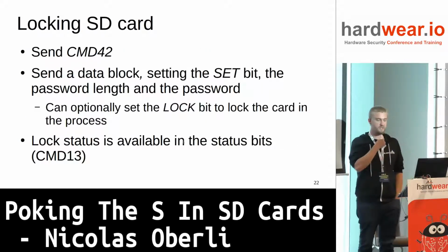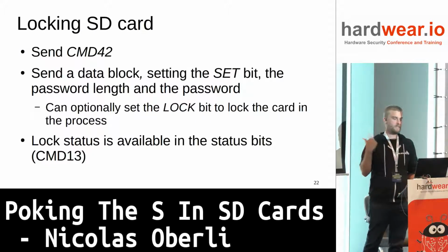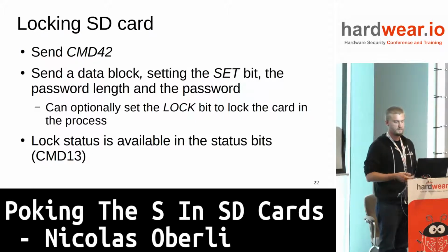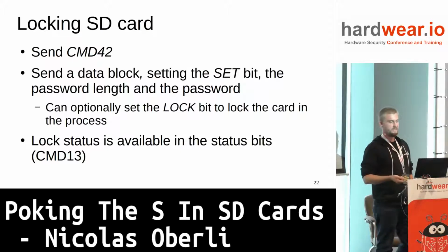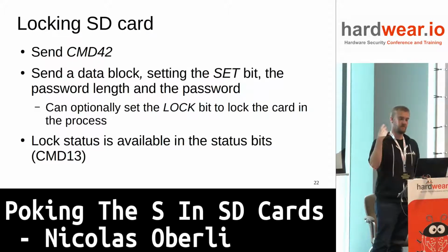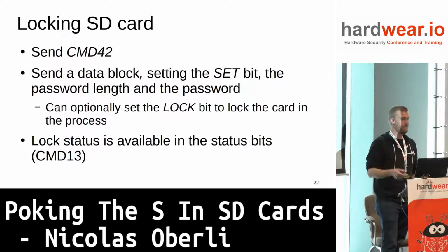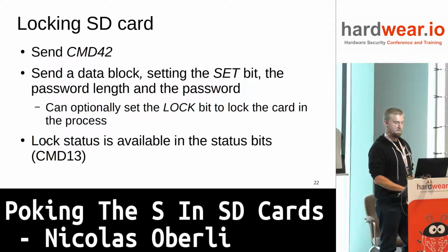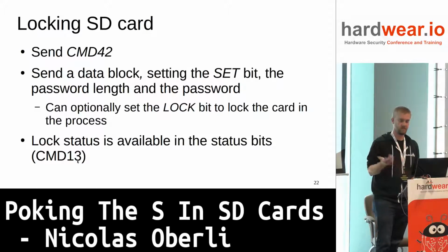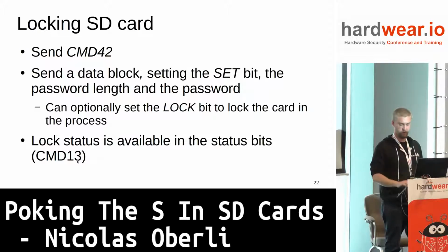So I started to play with that, sending commands to lock the card. Basically you send this block, you set the set bit. Actually, you can also in one shot use the set and lock bit. So once you put the password, the card is locked right away. And then to read the lock status, you need to read its status register, which is usually the CMD13, but in my tool you can just type status and you get the card status as well.